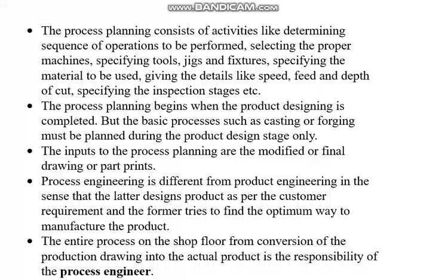If the basic process is casting, then at the design stage itself you have to think, we are going to design by casting, so these are the things we should keep in mind while designing. Or if you are thinking of producing by forging, then as a design engineer, you should pay attention to forging requirements at the design stage itself. But for the other miscellaneous processes apart from the basic process, you, as a process engineer, can decide at a later stage.